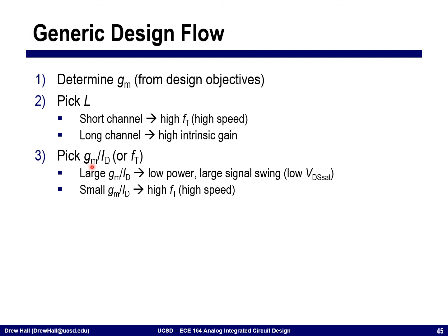All right, then we're going to pick either GM over ID or FT. It really depends on our design and what's more important, in the sense that if we're trying to design for high speed, FT is more important. If we're trying to design for higher gain, then maybe GM over ID is a little bit more important.